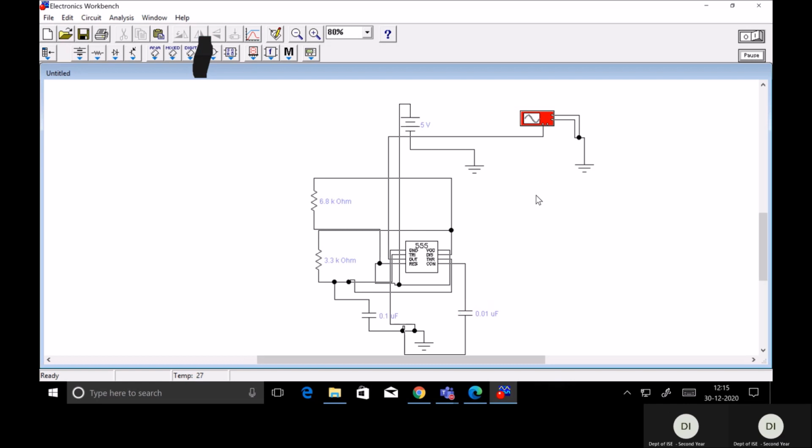Okay, so what I have done is from the third pin, I have connected a wire to the channel 1 positive. Next, we need to get a capacitor waveform, right? So channel 2 positive, the second point on the below of the CRO. So on the below, there is a second point. So what I will do is I will connect this second point to the capacitor. Why means,